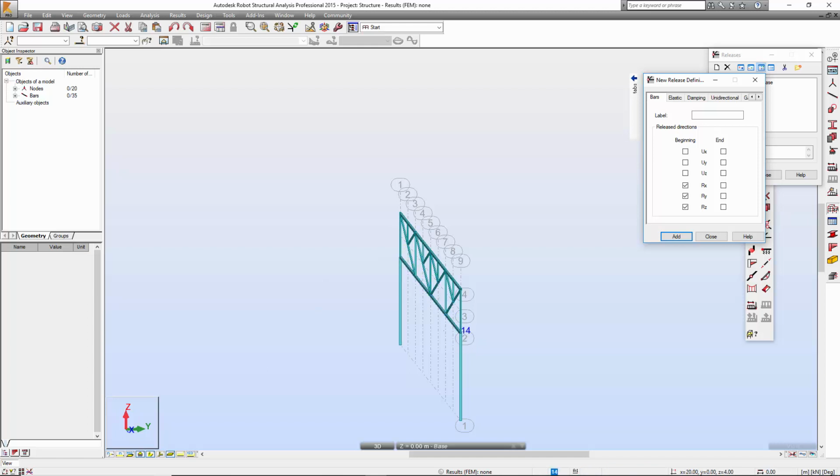So this is actually the x direction. So anything along the rx should not be released. Otherwise, this structure, as we said, is going to fall down in the out-of-plane direction. It may bend down and rotate about this axis. So this is not the correct way.